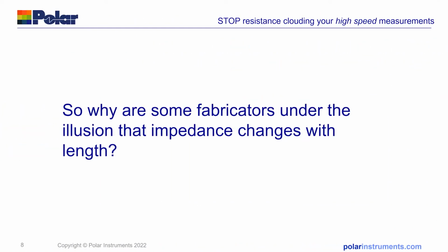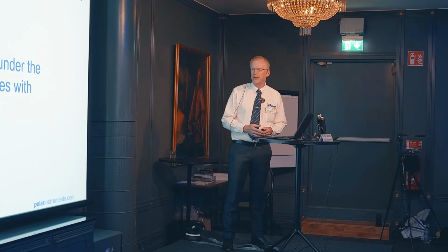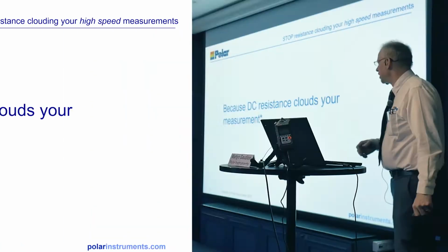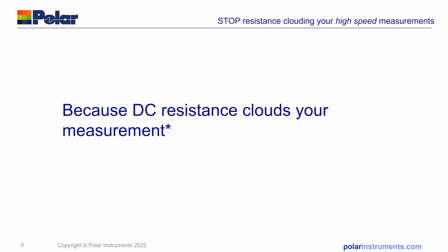This illusion that fabricators are getting that the impedance changes with length, it's really only crept into place as geometries have got finer and finer. What can happen there is that the DC resistance has clouded your measurement.